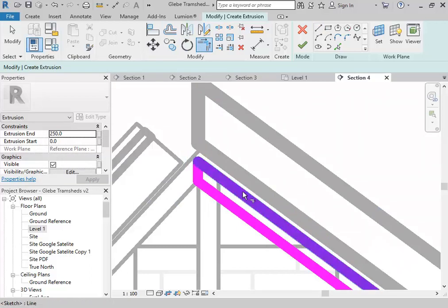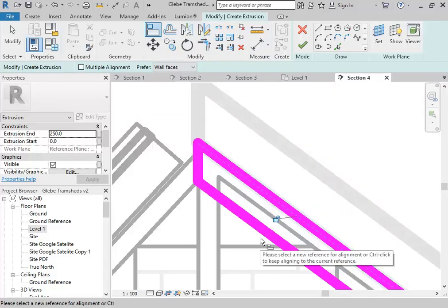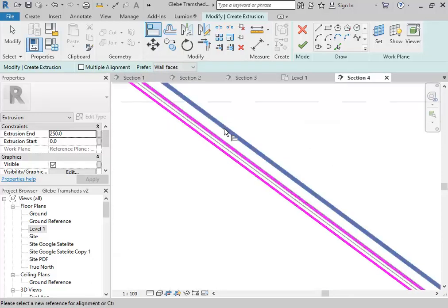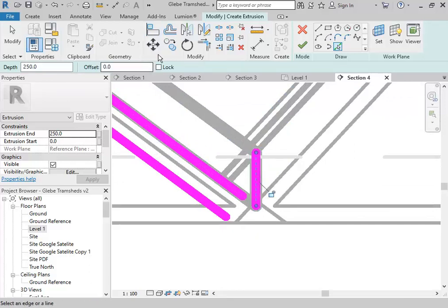And so that's correct in terms of construction, but to make it neater for the rendering, especially, I'm going to use a line, and then choose the bottom of the roof, and then bring the ceiling to touch that. So there's no gap. Yeah, that's right. That's it. So then down on the bottom, I'll do the same thing. So I'll pick the line from the roof, and then use trim to join that together.